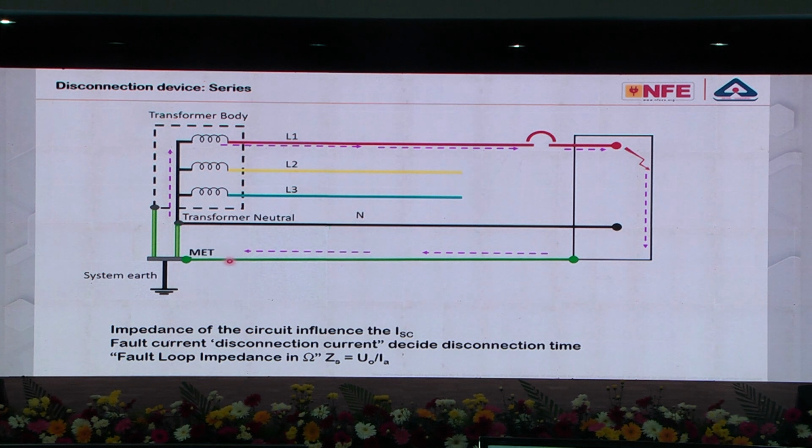And everywhere the tender specification always says 1 ohm earth electrode. 1 ohm earth electrode. From where has this come? Nowhere in IS 3043 for a low voltage application is this written. Nowhere. Sorry, I am stressing it again and again because this is one of the most important points. We have an earthing session in the afternoon.